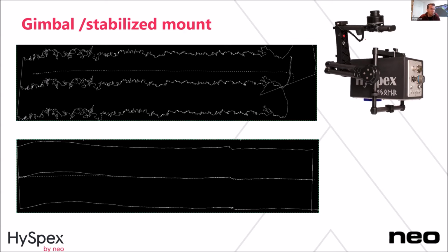So your pixel size on the ground when you're not using a gimbal will be very much distorted relative to when you're using a gimbal. That's why a gimbal is highly recommended for all copter solutions. Helicopters, you are okay with the damped platform. But octocopters, this 25 kilo UAV, we definitely recommend a gimbal.